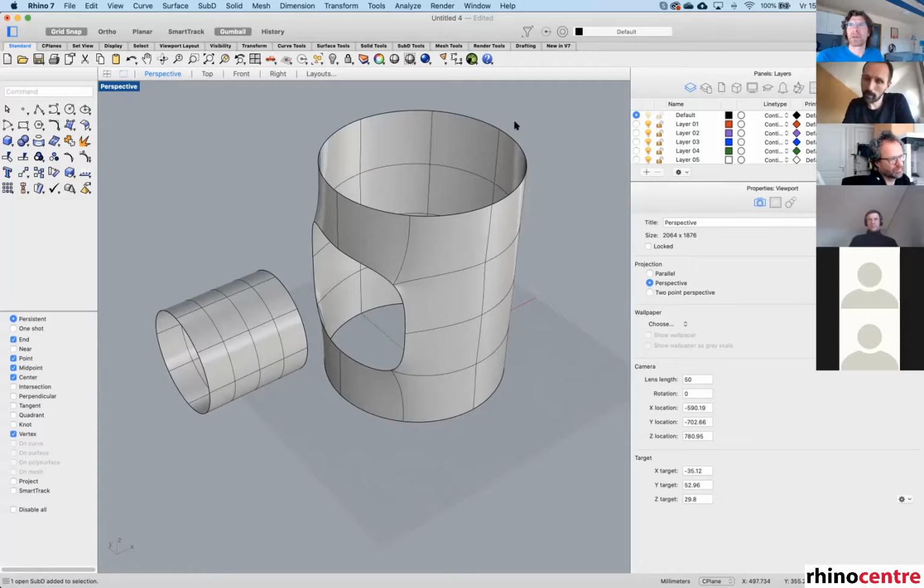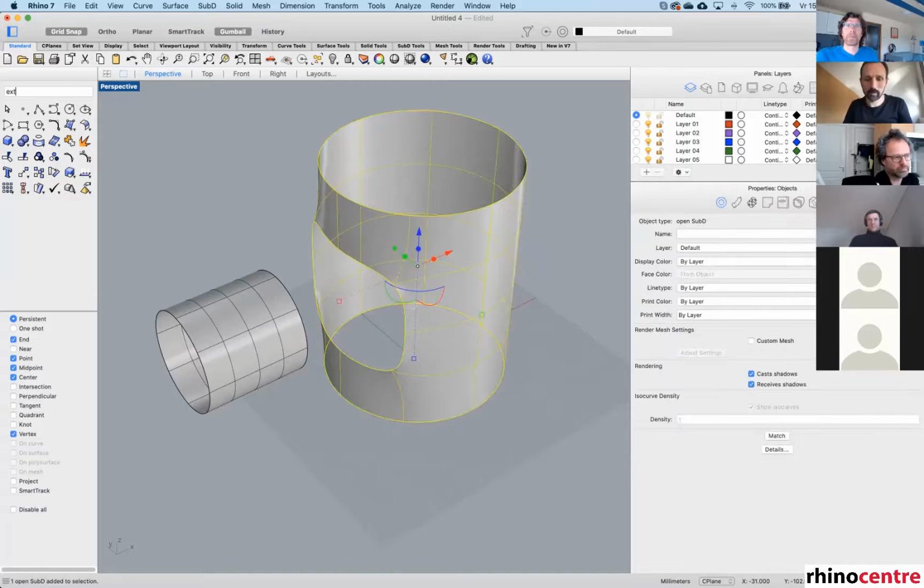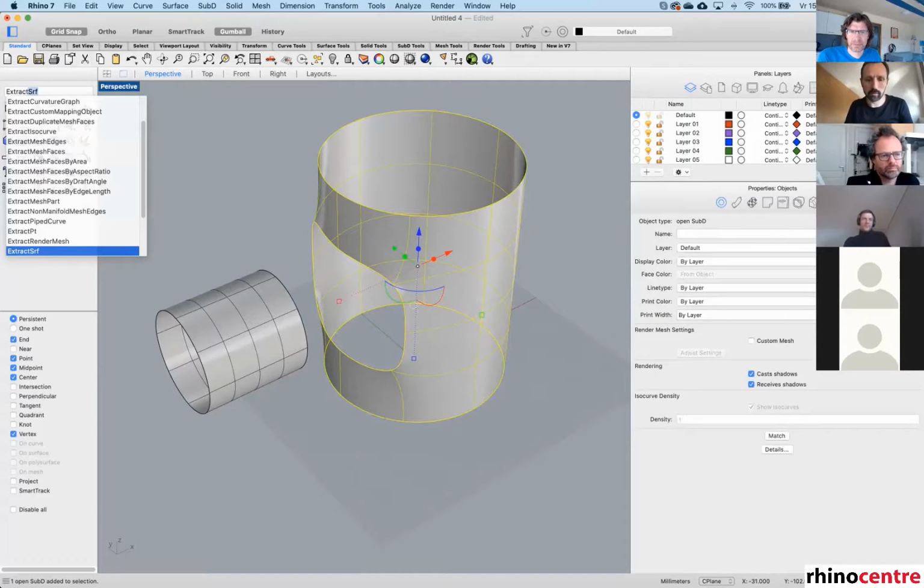So what I found out as a current limitation of subdivision modeling is the lack of analysis tools for curvature analysis, surface continuity, etc. That's for me a big issue, because from a fairing point of view of ship hulls, you want to examine the quality of your result. And it's not really useful to convert over and over again to NURBS and then analyze that NURBS.